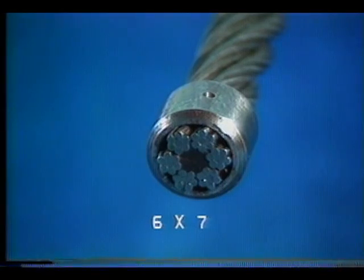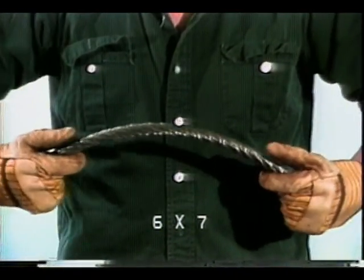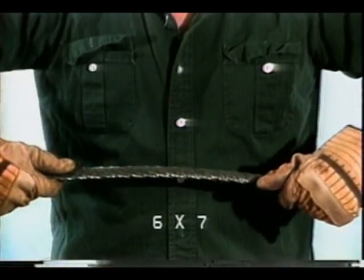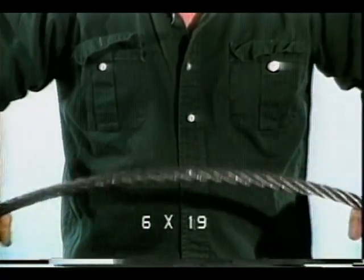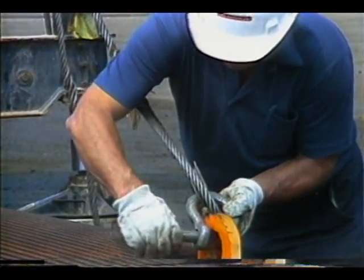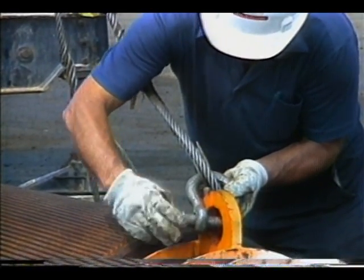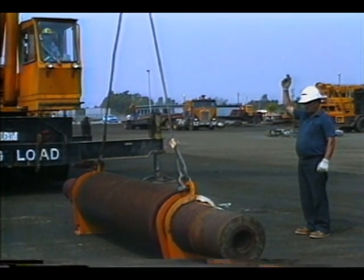The least flexible is 6x7. It is mainly used for guy wires and other stationary applications. It can be either wire rope core or fiber core. The 6x19 construction is more flexible and one of the most commonly used wire ropes for slings. This classification covers ropes with 6 strands having 8 to 26 wires per strand. These two can be IWRC or FC.